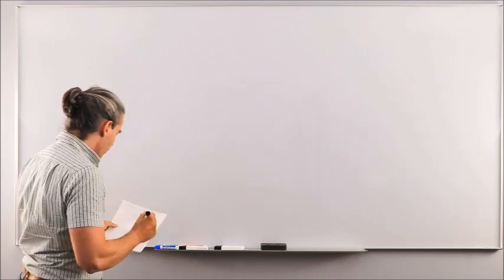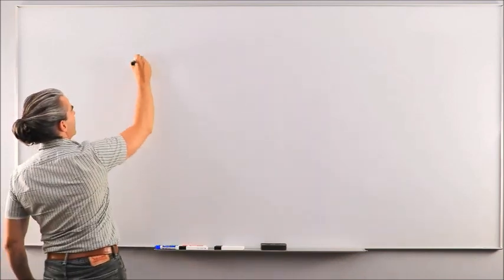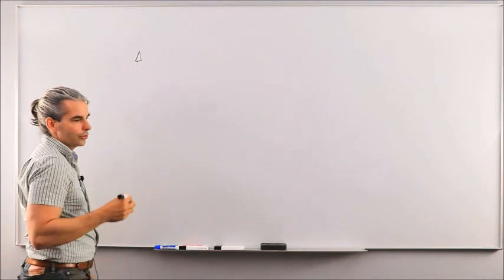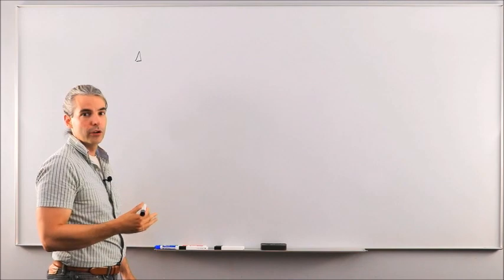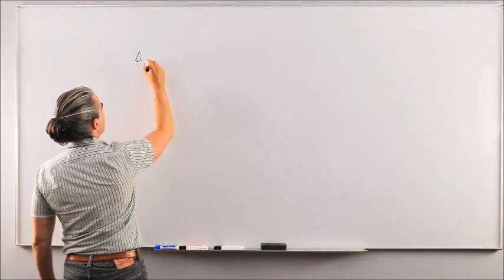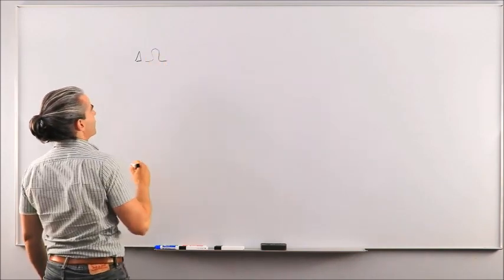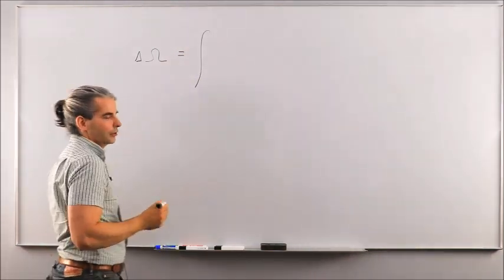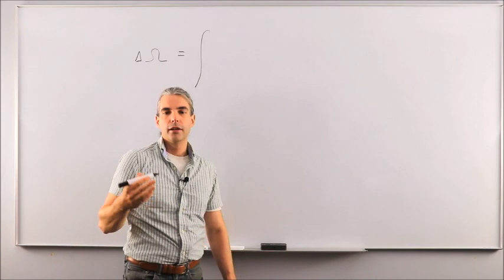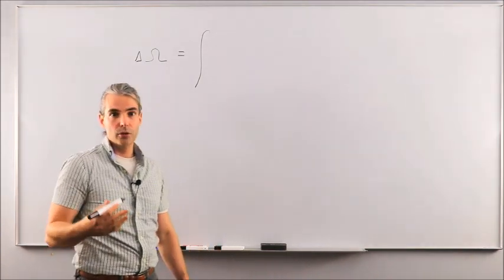Last time we were about to derive the secular variation due to J2, and specifically I said we were going to do the work for RAAN. So, secular variation in RAAN. If you remember, the trick is to do the integral over the true anomaly instead of over time.